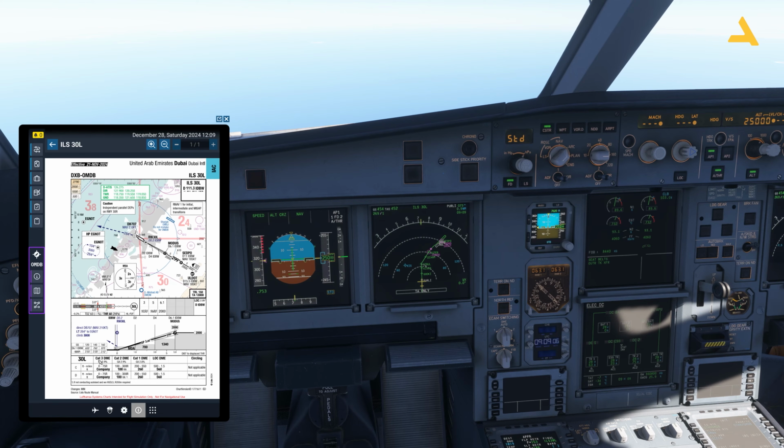Category 3 is the highest level of precision. Then you have category 2, which is lower than category 3, and so on and so forth. A DME actually stands for distance measuring equipment. So it's actually a ground-based navigation aid, the localizer, which you will be tracking for the ILS, and get the distance. So that's why it is a DME.